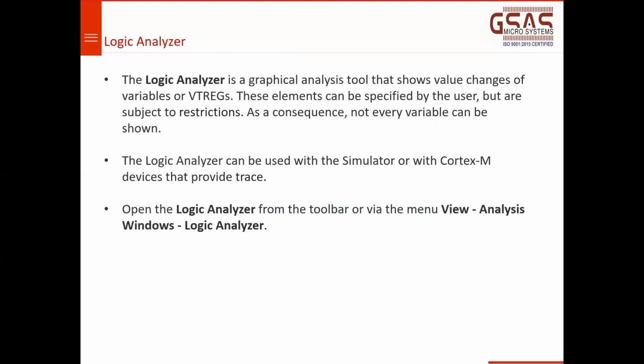Okay. So the logic analyzer is a graphical analysis tool. I'm not sure whether the team on this bridge has used this feature. It is available for both simulation and hardware, specifically for Cortex-M. You see graphical analysis of your application, or whatever variables you use in your program, or the virtual registers. Whatever virtual registers are used in your C script can also be added to the logic analyzer.